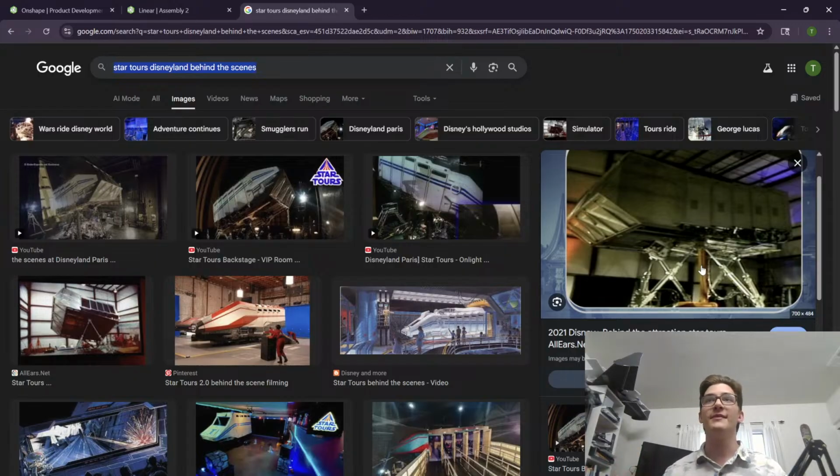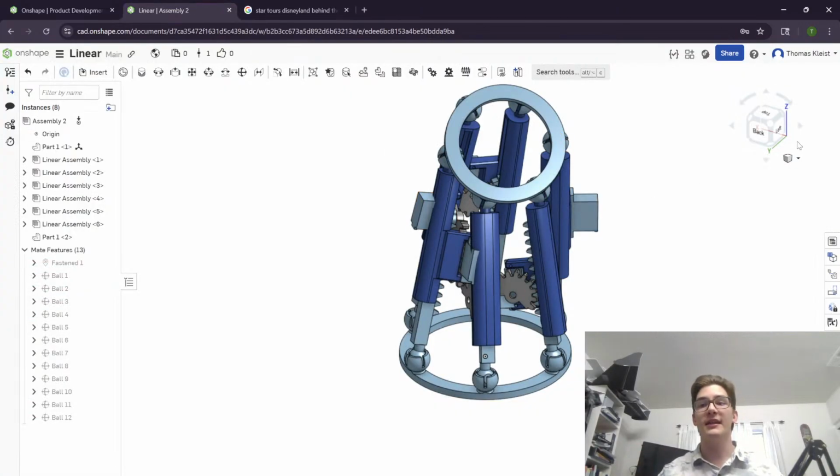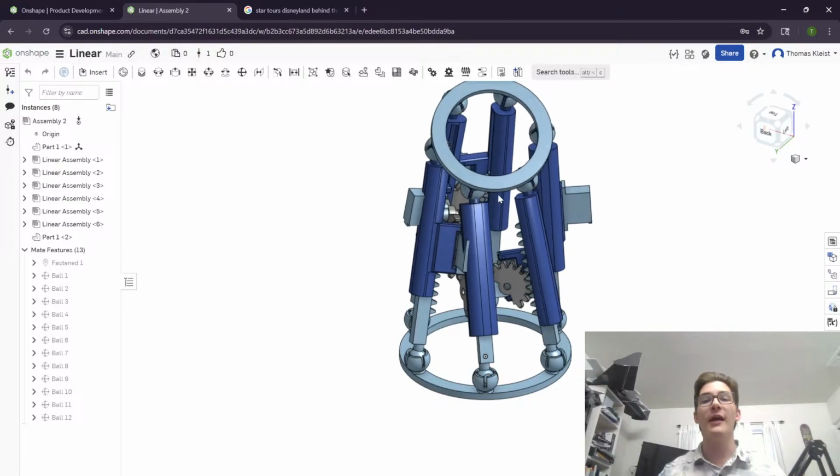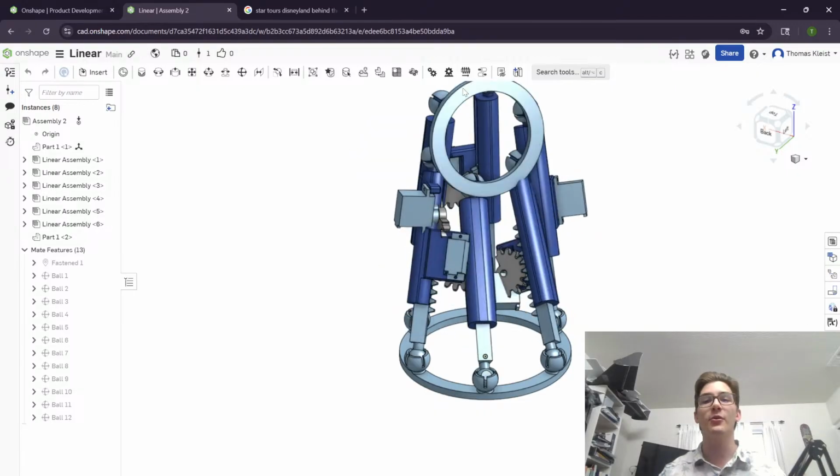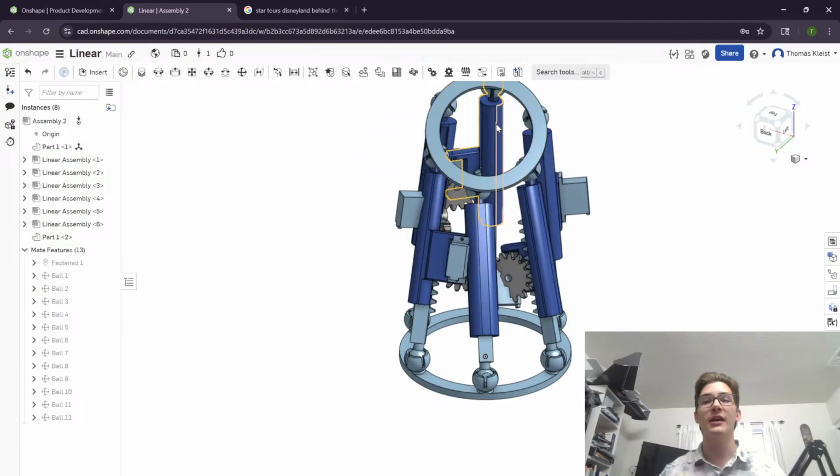So you have to do very specific math to calibrate how you drive these linear actuators and get all the correct positions for whatever movement you're trying to create. With the 8 actuator system, it's even more intense because there's even more ways to mess that up, but it does provide a lot of rigidity. So if we go back to my design, I'm using 6 actuators because that's the minimum required in order to get that 6 degrees of freedom.